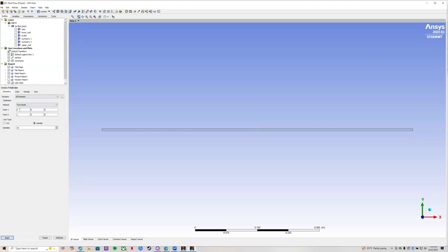And then we're going to put this at that very end so we can get data from midpoint and at the very end of our pipe. Make sure to put the height in there and make it 100 samples. Fine, we get our little line all the way to the very end.